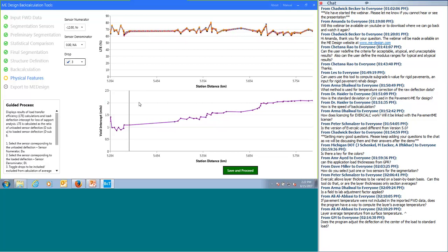And if you remember from what I indicated that was shown by the cores, the first half of the project was really pretty good. The second half of the project was where we started seeing stripping, where the hot-in-place recycled material was used, and from one end to the other, the stripping got more and more. And you can see the void interpretation, the more and more stripping observed by the cores, or the more loss or surface disintegration, you can see that the intercept started increasing, and then it finally exceeded 2.